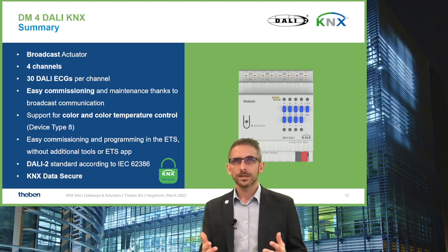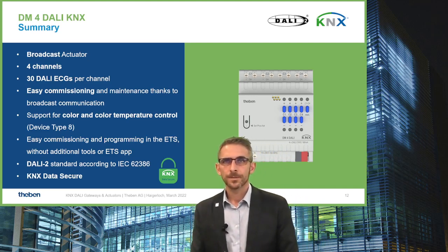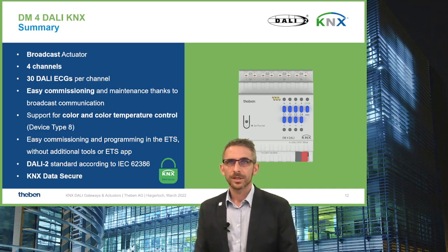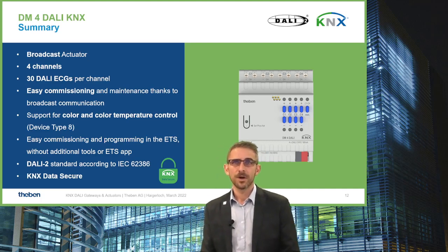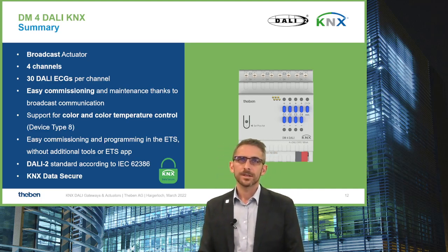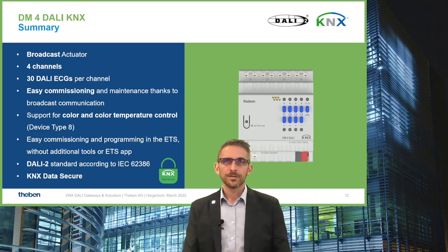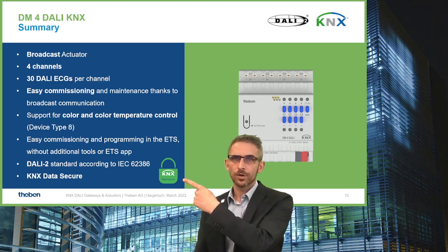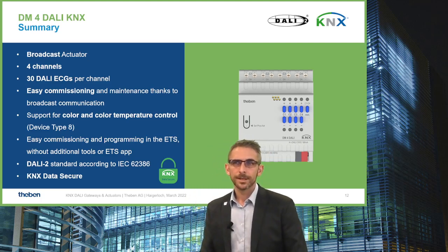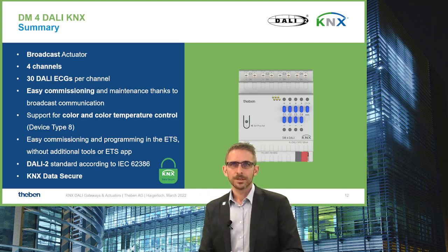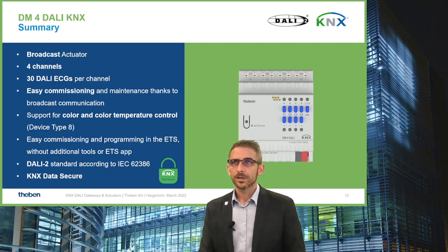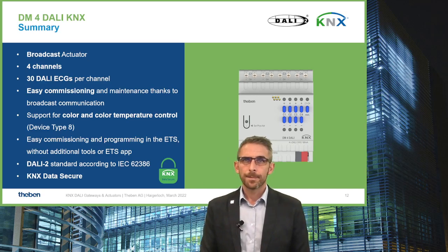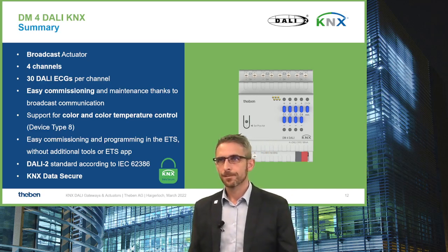We do not need an ETS app for the commissioning. So the ETS application is very, very simple. And yes, the device is definitely following DALI 2 certification or DALI 2 standard. And we have included secure communication following KNX Data Secure, like we have it with all current and new KNX devices in our range.